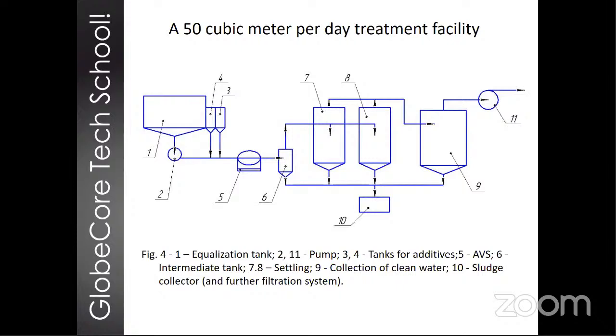In this line, water can be passed simultaneously through one or two filters, depending on the actual volume of water. According to the information we received from our customers who have already installed such process lines, if the velocity of the water stream is about 5 meters per hour, the continuous operation time of one filter is about 40 to 50 hours, after which the flow of water is switched to the second pair of filters. Pump 10 does that, and the spent filter is washed with the water supplied by this pump for about 10 minutes.